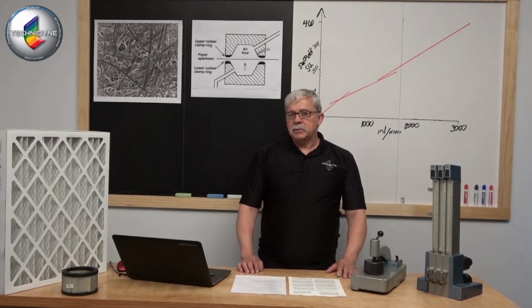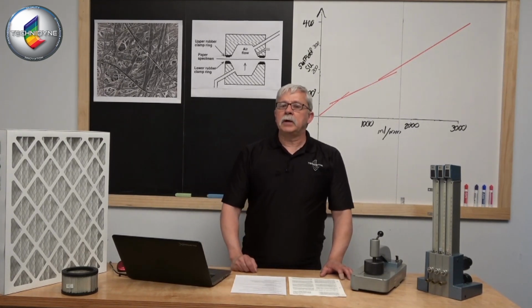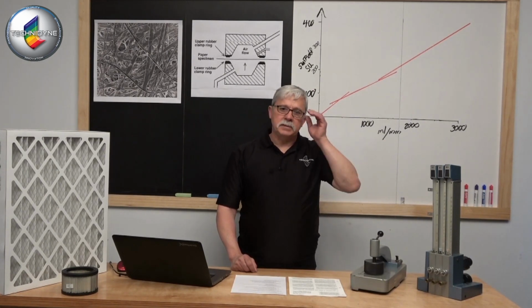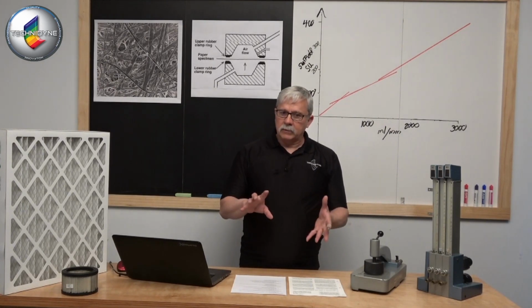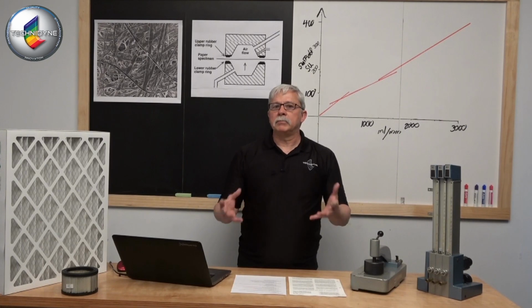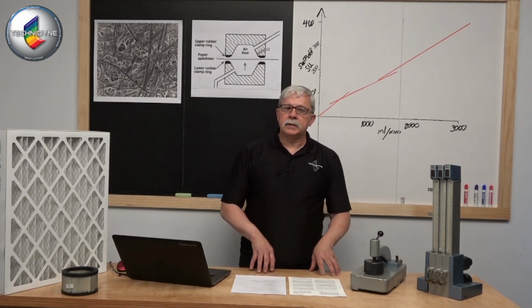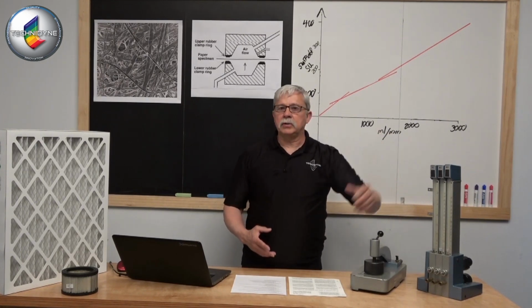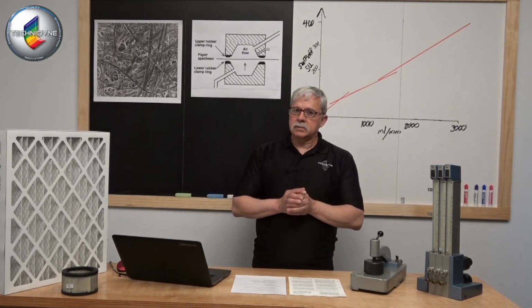So, as I mentioned, the 3/4 inch orifice diameter became, maybe not by design, but by happenstance, the most popular. For the other orifices that are available, if you have a more open sheet, one way to reduce the amount of airflow and still be able to measure within the working range of your measurement system is to neck that orifice down.